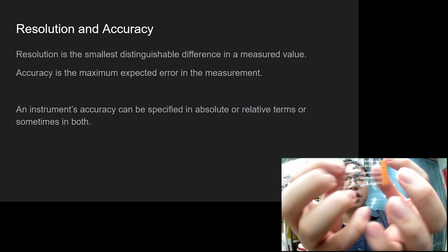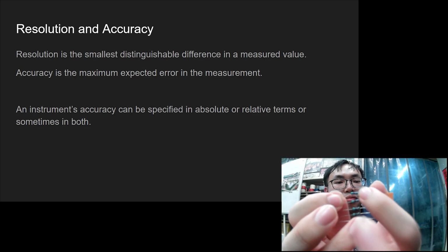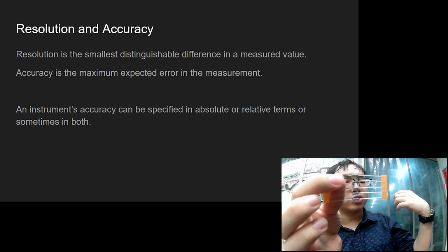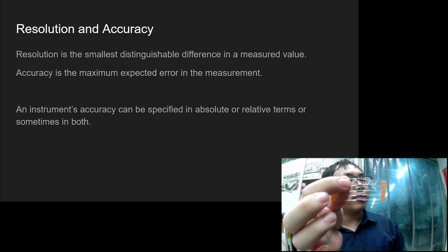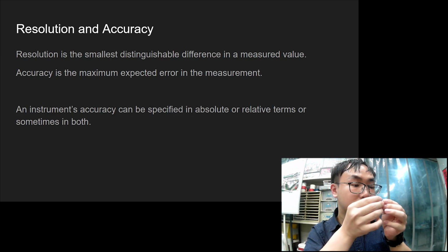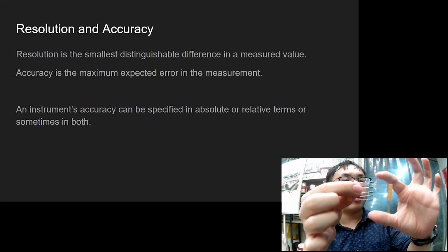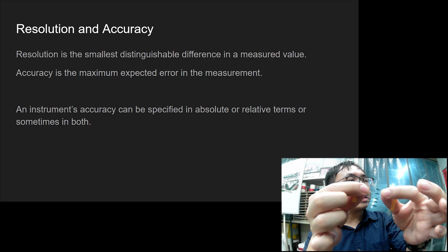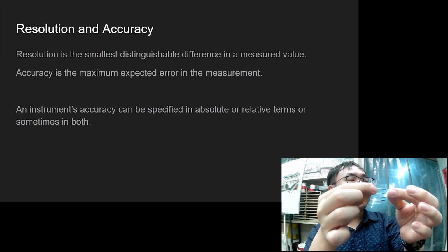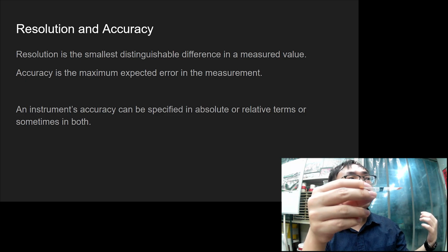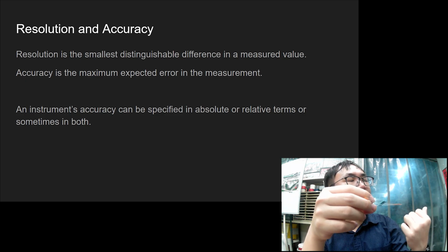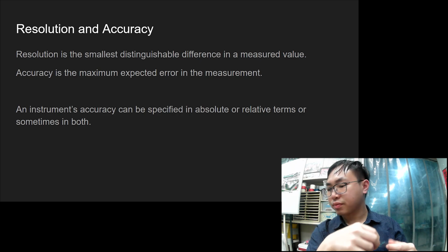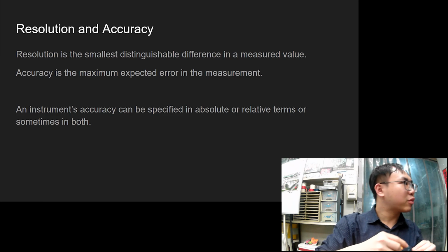the resistance here. The last band is in brown, okay? So you can check your percentage, check the chart. Brown is how many percent? Or is it black? Also, you can Google how much percent the accuracy of it. So it's expressed in percent. For example, a 100 ohms resistor having a 5% accuracy, so it ranges from how much? You can calculate yourself. I'm not going to calculate here.